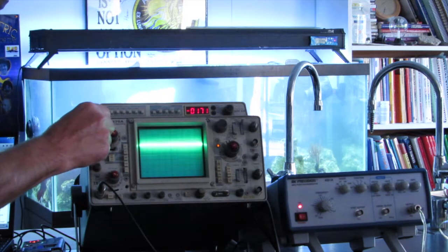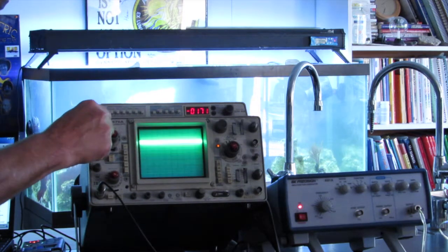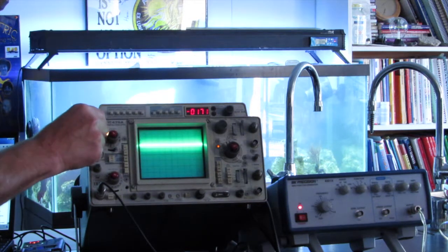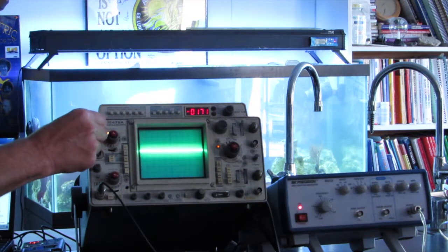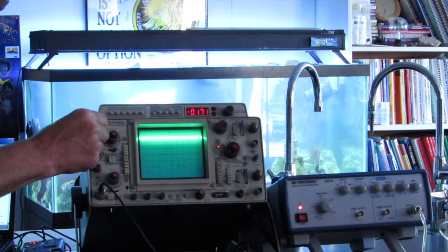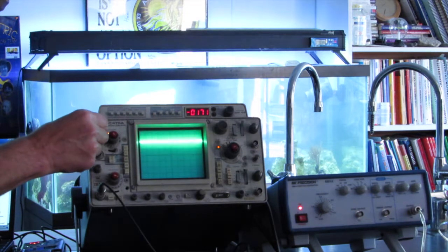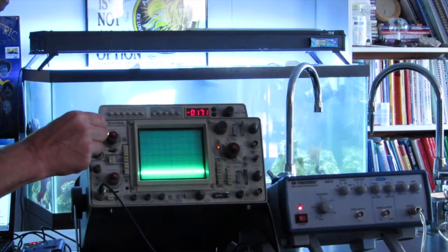It does not. What this does is when there's nothing plugged into the channel, or if the channel is set to ground, which grounds the probe, wherever you put this is just your reference. That would be like the negative side of a battery if you want to measure the voltage on a battery. And you can set that wherever you like to be convenient.